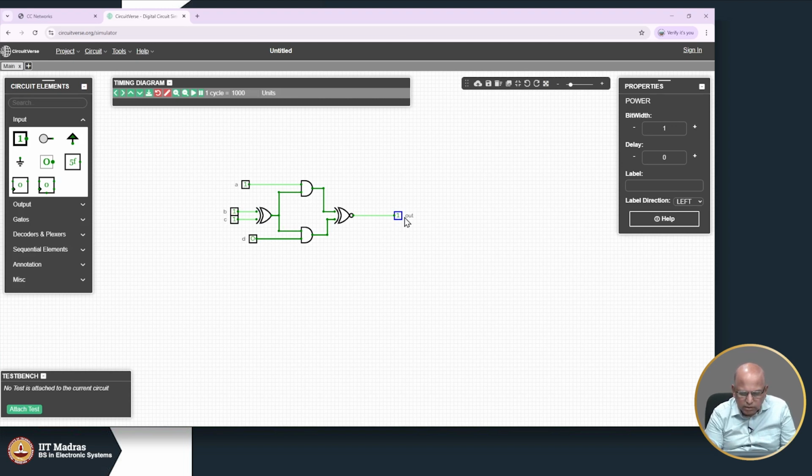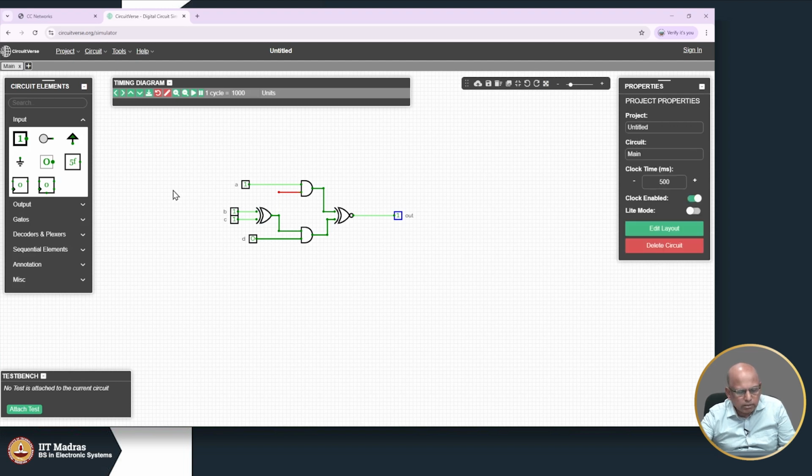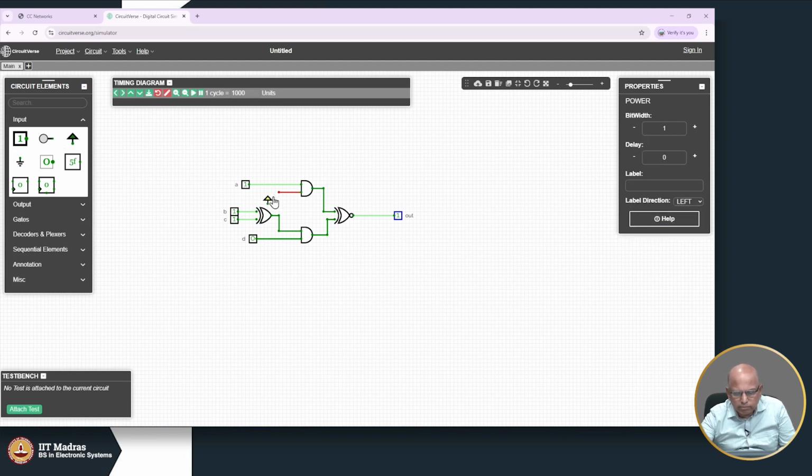But if I go back to the same thing, see, this changed. Okay. So that is a way to argue why 1 1 1 0 is a test vector for a stuck at 0 fault on this wire. Okay. I want you to be able to do this.